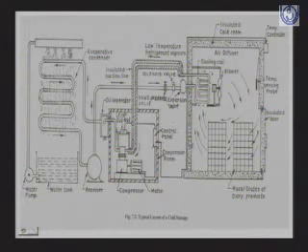Normally the cold storage is of this type. You can see these are the product racks where the dairy products are kept. This is an insulated door. This is a temperature sensing device. These are the cooling coils. Here the blower is there, which will blow the chilled air into the cold storage, and the cooling will take place. This is the insulated cold room.